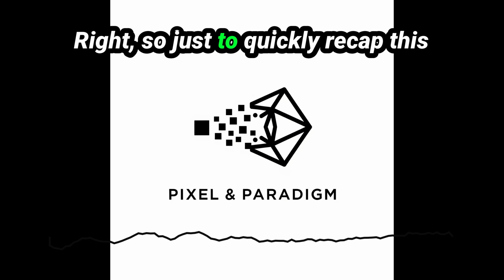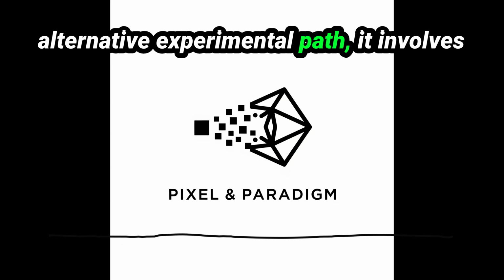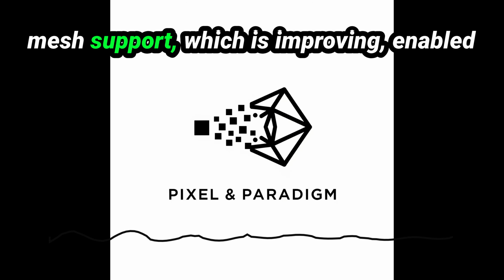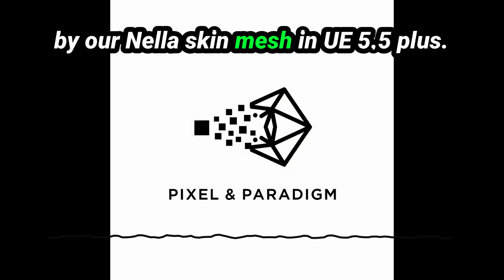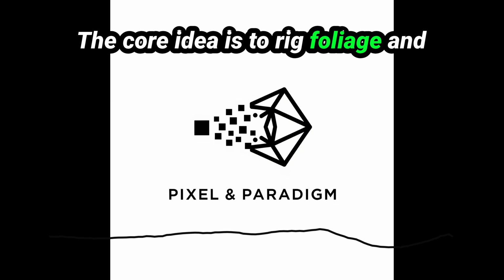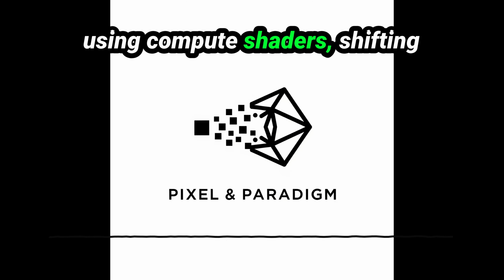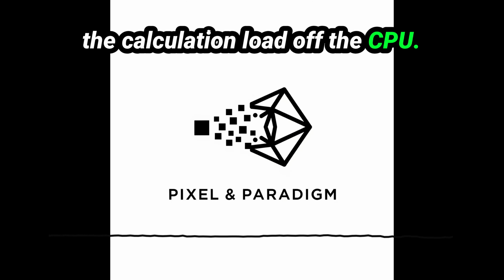Okay, right. So just to quickly recap this alternative experimental path, it involves using Nanite's experimental skeletal mesh support, which is improving, enabled by Nanite skinned mesh in UE 5.5+. The core idea is to rig foliage and aim for GPU-driven bone animation using compute shaders, shifting the calculation load off the CPU.